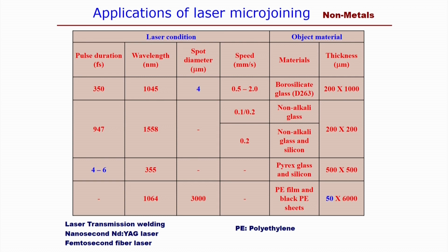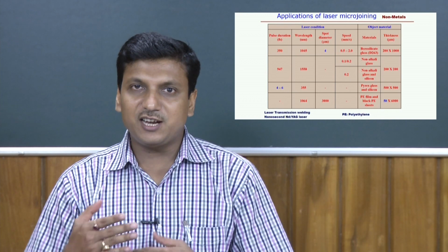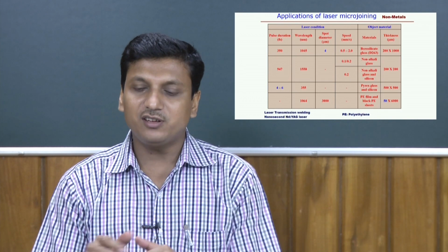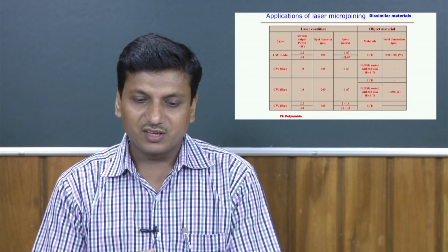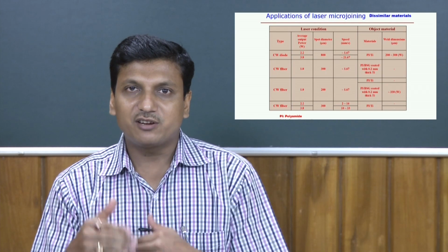So, mostly the non-metallic materials are processed in micro-scale applications using the femtosecond pulse laser, in the mode of laser transmission welding. Now, dissimilar material combinations can also be welded in micro-welding applications.